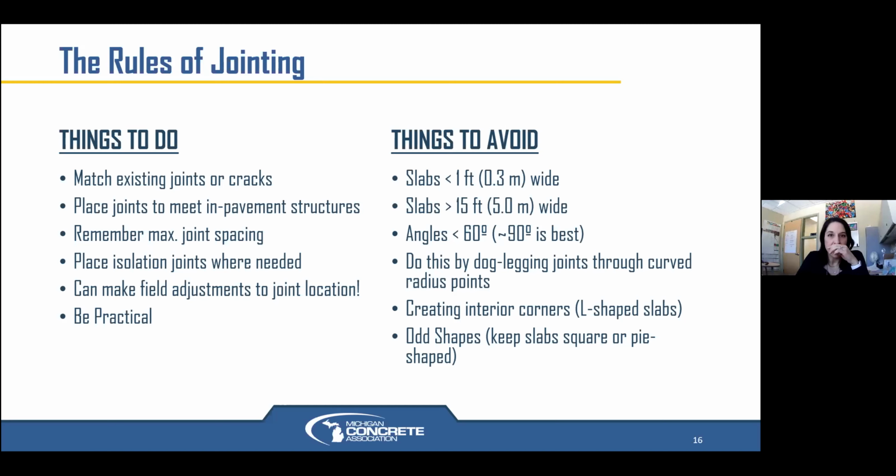Heather, I want to point out, just in our question and answer, slab thickness, polish in use, base stiffness, and friction can also be factors to consider when sawing.